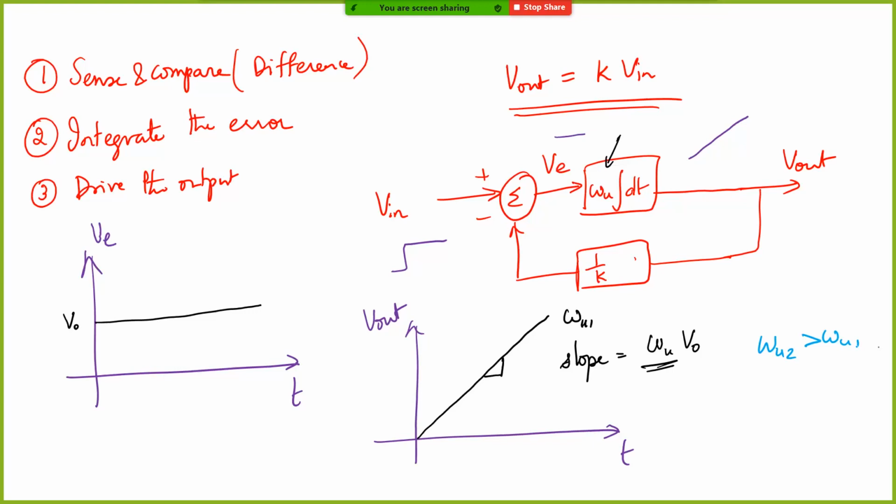Yeah, so this is an integration, right? If you just have only integration dt, you have this factor of time. If you look at the dimensionality, there is an into t. You integrate, so you have into t, but the output has to be voltage. So you need a constant which has a unit of second inverse.